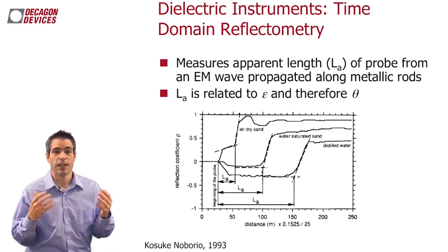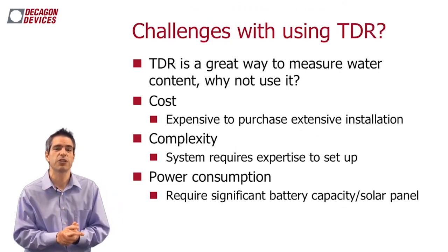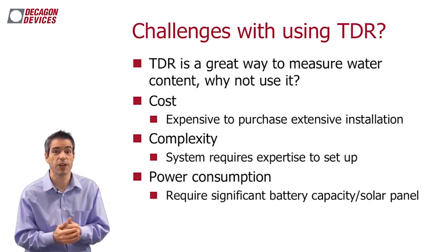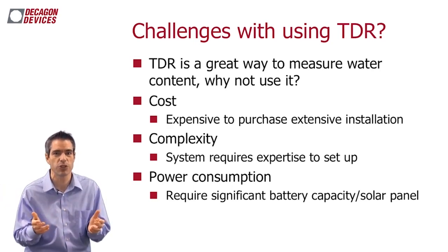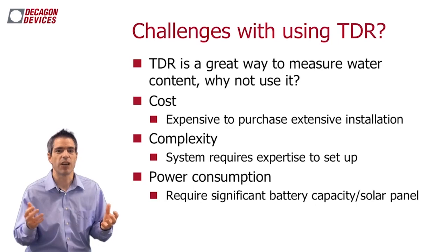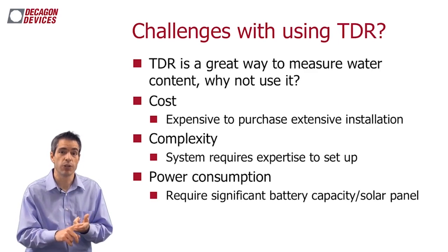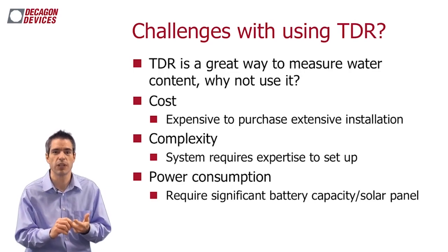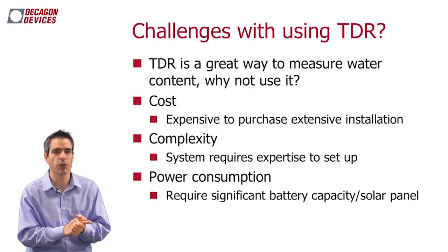Now, what are some of the challenges to TDR? Well, TDR is actually a great way to measure water content. Why can't we use it everywhere? It actually does work very, very well. It suffers in the high clays. That's been well documented more recently in literature. There was a feeling at one time that it works in every soil anywhere, but we really know that is not true. There are some areas where we need to do another calibration, but with a better calibration and better analysis techniques, especially that are starting to appear in the literature now, we can get good values out of this measurement, even in those difficult conditions.